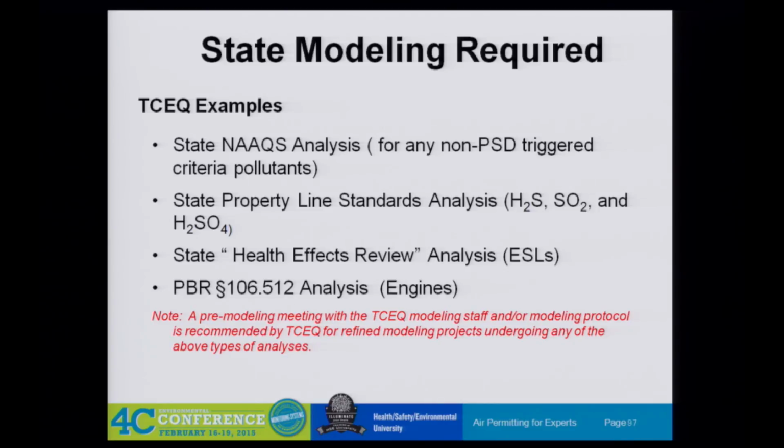So you're just modeling, if you don't change your PTE, your potential to emit, or your permit allowable, you don't have to model that source. It's 0, right? And that comes into play a lot for your affected sources like your boilers or heaters. Say you need more steam demand, and you might have this giant, enormous PTE of your boiler, and your steam demand is going to take up a little bit of that.